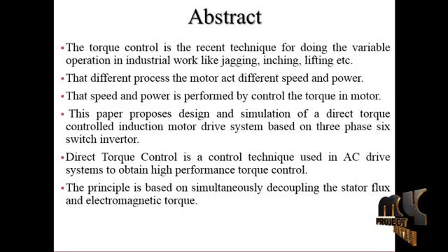In recent years, direct torque control strategy of induction motor drives has been widely implemented in industrial variable speed applications, introduced in the middle of the 1980s. The first DTC strategy involves a simple control scheme which makes rapid real-time implementation possible. Since then, several investigations have been carried out to improve the performance of the original DTC strategy. The major focused features are the uncontrolled switching frequency of the inverter and the high torque ripple resulting from the use of flux and torque hysteresis control.